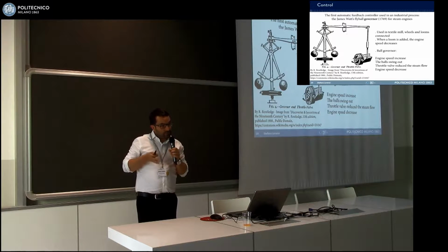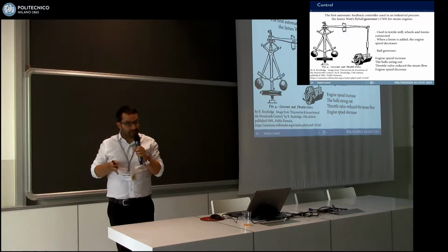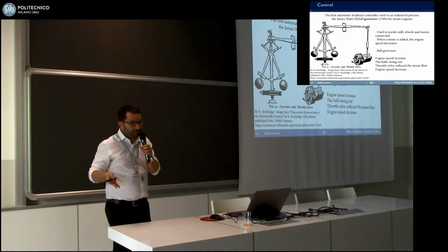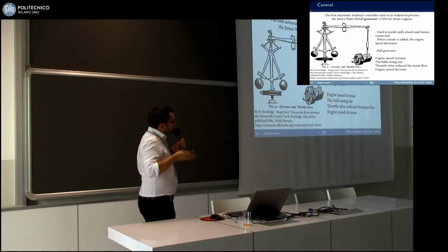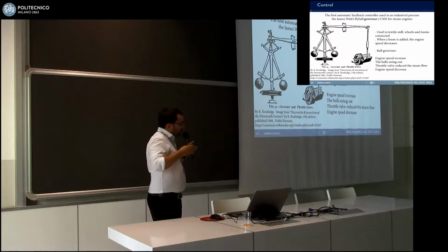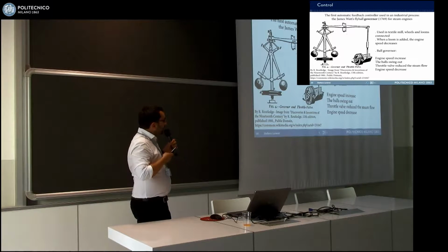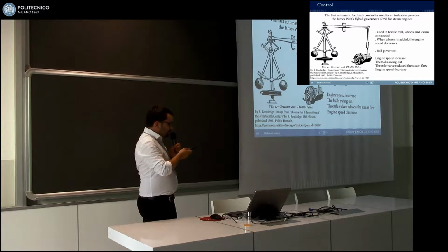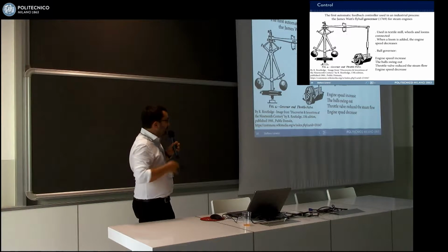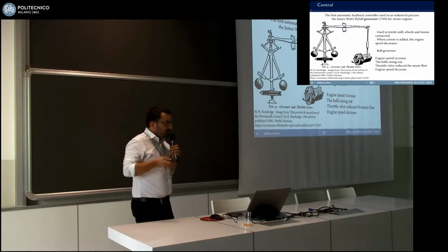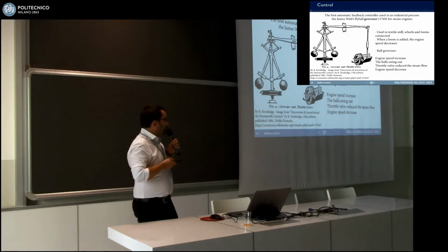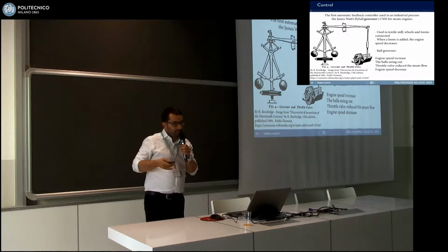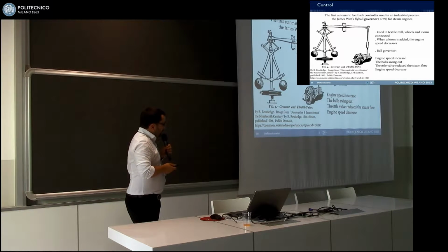Actually, this is more or less the same thing that happens in the electrical grid. In order to keep the frequency of the electrical grid constant: the frequency can be affected by load and by power plants. If a load is added to an electrical grid, the frequency of the grid decreases. So in a modern power plant, there is a controller that acts on the turbine admission valve in order to regulate the power.